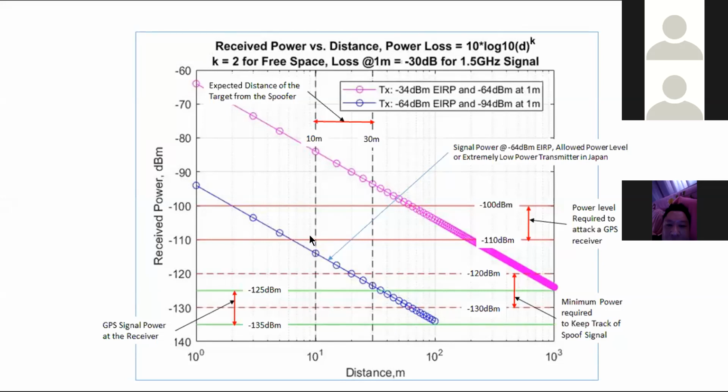And that means the interfering and jamming will have a very similar effect on any type of GPS signal. So we take the GPS L1CA signal as a reference to study all these jamming, interference, or spoofing issues in terms of the power or signal design. Maybe some other signal like L1C is 2 or 3 dB stronger, but not so much. So this is the point that I would like to highlight, why this 24 dB or 22 dB cross correlation value is very, very important for the interference issues.